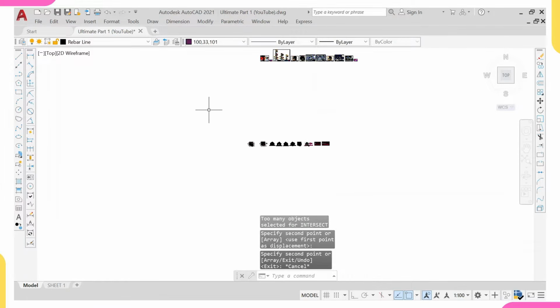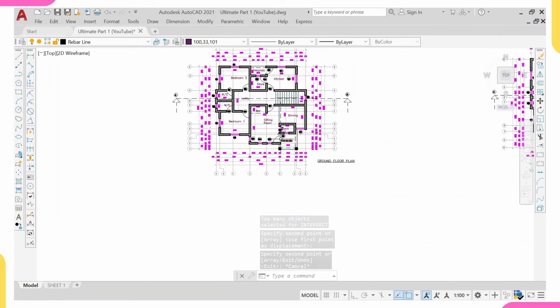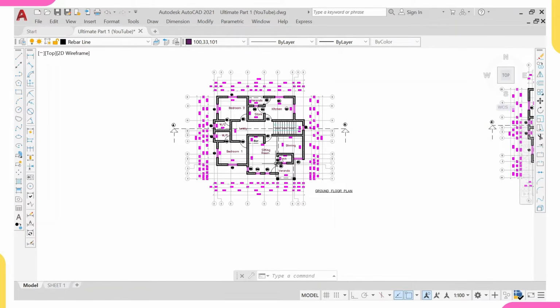After copying out your architectural plan, the next thing that you have to do is to study your architectural plan. First, you study the architectural plan. What's the building used for? Is it a residential building? Is it a commercial building? We have to know that if it's a residential building, the loading will be different from a commercial building because they will not be having the same dead load or live load applied to it.